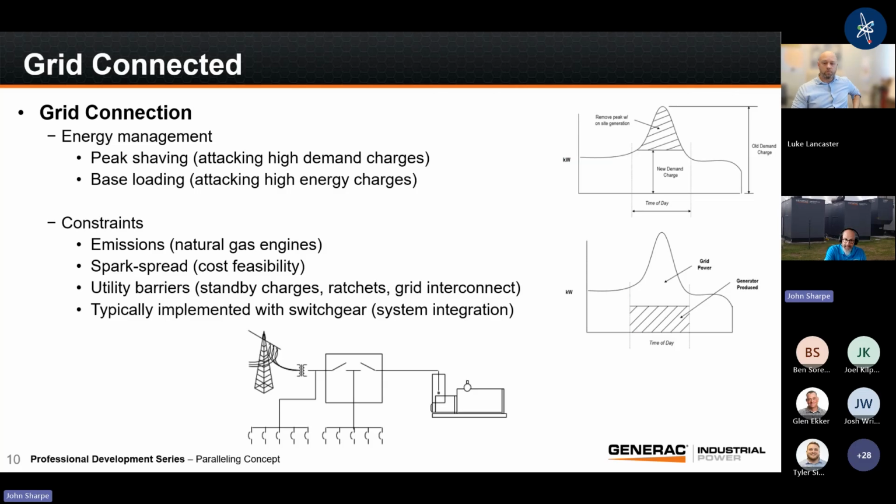I'm going to say, all right, give me 75% load on this piece of equipment. And then anything that goes above that is going to come from the utility. So you minimize your energy spend. So you look at the two different parts of a power bill. One is minimizing demand, right? KW. The other is minimizing KWH, which is energy consumption.